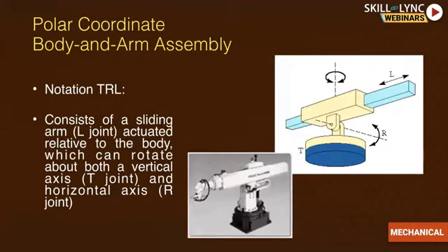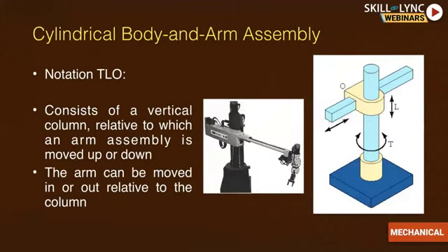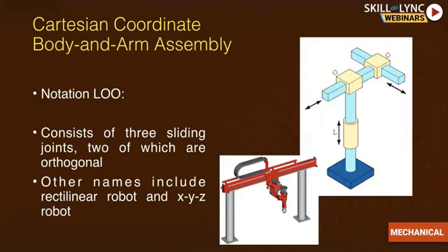And also a robotic arm can have different configurations. So this you can see, this is a polar configuration. So you have 3 rotations. Okay, we have three joints, and all joints are rotational joints. Here you can see we have 1 rotational joint and 2 sliding joints. This is called a cylindrical one. So T is nothing but the first rotation. The L and the O, those are your translations. Translation means you have sliding motion, and you can also have all 3 sliding motions, which you can see in your overhead crane, that gantry type of manipulators. All those fall under this category.